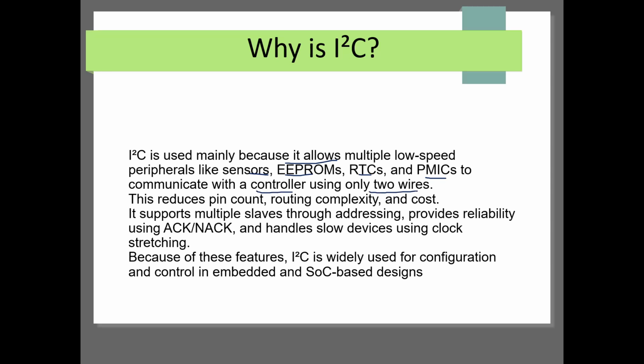Only two wires we use to communicate with sensors, EEPROMs, RTCs, and PMICs. So it reduces the pin count, because only two lines are transmitting the data. Routing complexity is also less, and cost is also less.